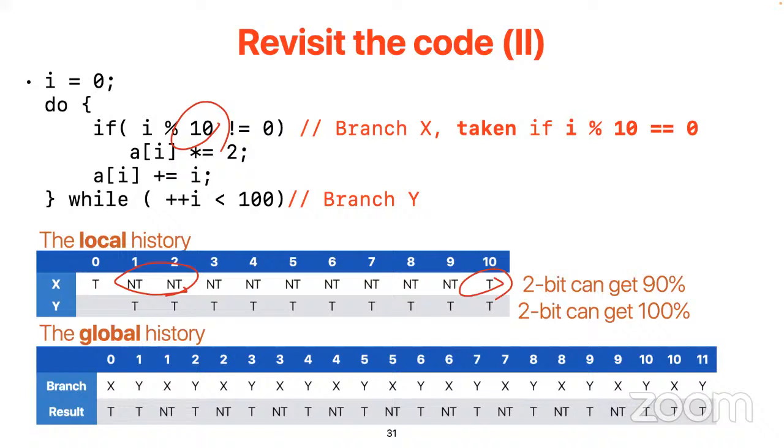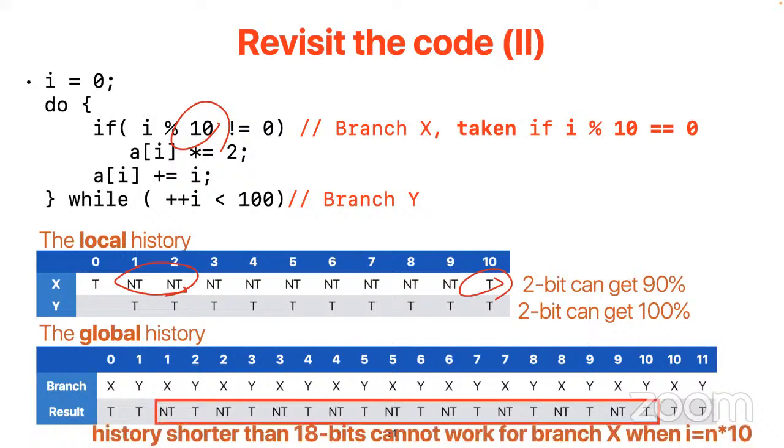And for the global history 1, the pattern is actually this long, right? So you definitely need something to have this correct. Although the pattern here seems pretty well behaved, for everything like this the global history could make a good prediction. However, for this one, that's really not something the global history 1 could help.